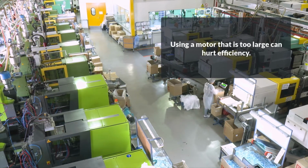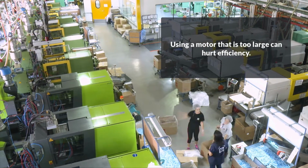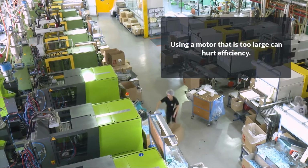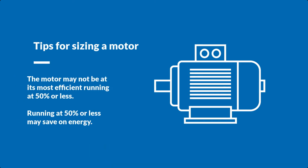Oversizing a motor to give it a safety factor may provide plenty of torque for the application, but efficiency just took a hit. To size a motor and drive system to operate more efficiently, run it between half to full load. Optimal efficiency is at approximately 75%.